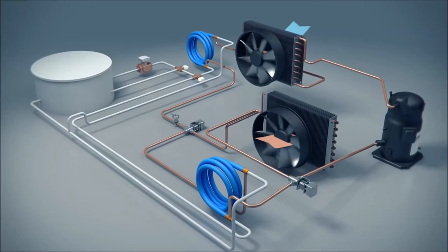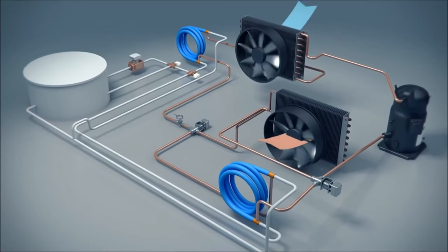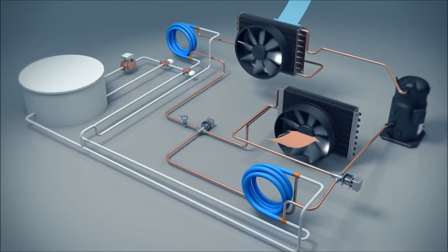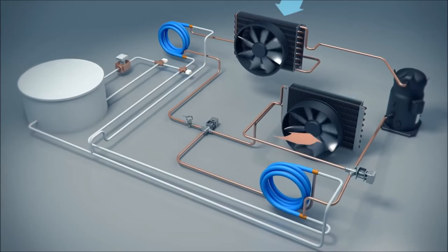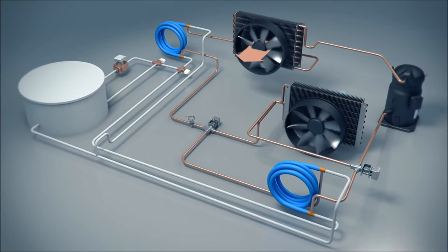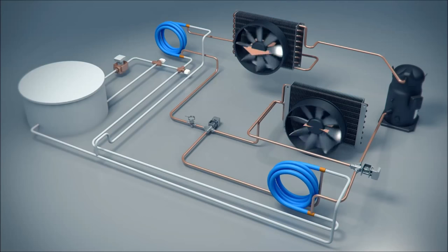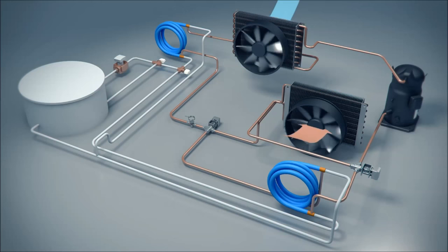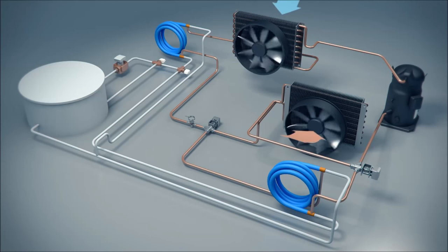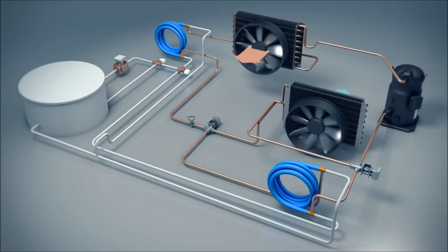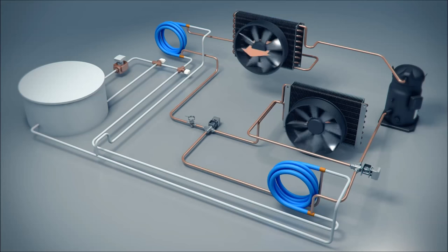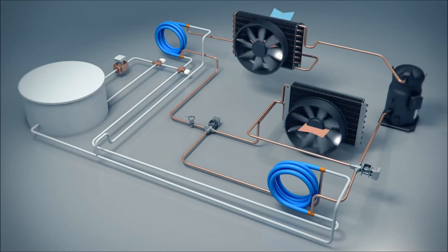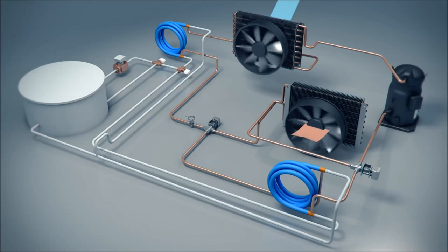It is known that a refrigeration cycle is adversely affected when subjected to elevated ambient temperatures at the system condenser. When the cooling demand is held constant at the evaporator and the condensing ambient temperatures are allowed to fluctuate between a low of 45 to a high exceeding 100 degrees, the system experiences an increased energy consumption at or exceeding 30%.